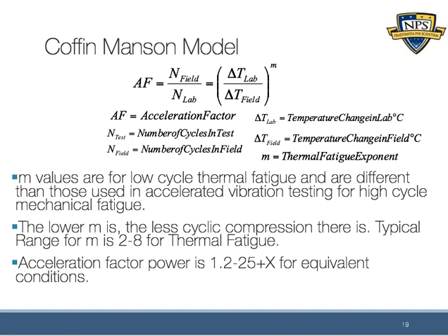The model shown on this page is the Coffin-Manson model. It has some similarities to the Arrhenius model, but in fact it's used specifically for temperature cycling. So this is a really good one for modeling things that have CTE mismatches across their life cycle. Or if there's a failure in a part, let's say during manufacturing, and you're concerned about whether it will last a lifetime, whether that failure from manufacturing is important, then this would be an appropriate time to